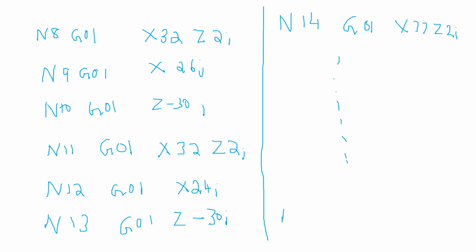And finally you need to close the program. It might be reaching N37, 36 or anything, it goes on. I'm not going to do it over here, you will be doing it. It will be N36 M09, which is stop the coolant. I don't know what the line number will be according to what you did.